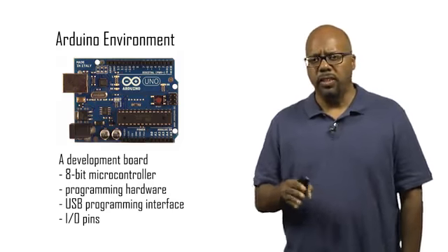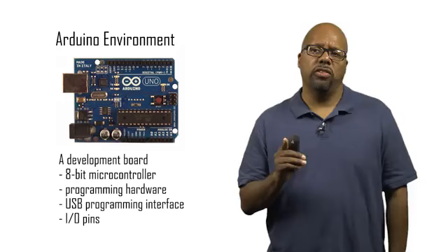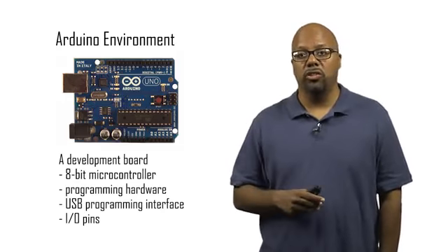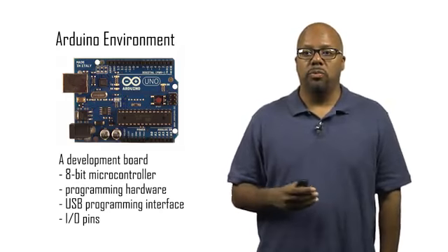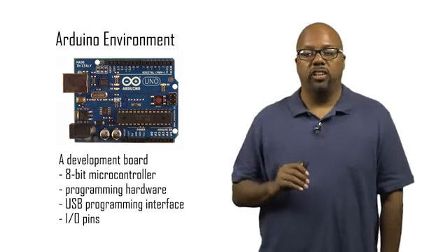So there's hardware in there. Just behind the USB cable is a chip that communicates with the USB and allows you to transfer data to the microcontroller. So that's the USB programming interface. There's also software on the Arduino, the bootloader, that handles that too.